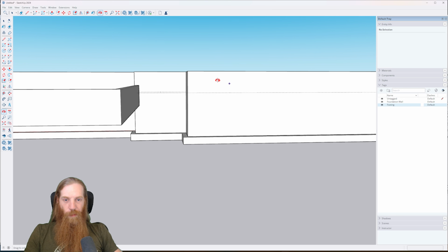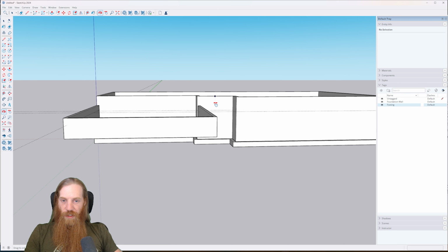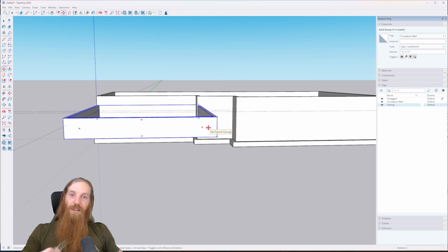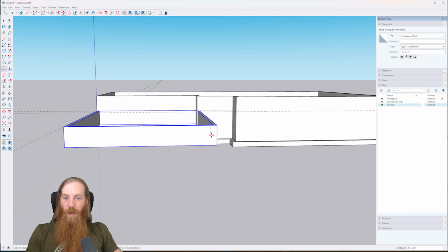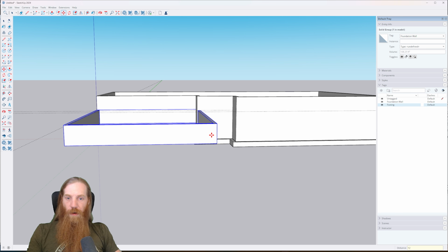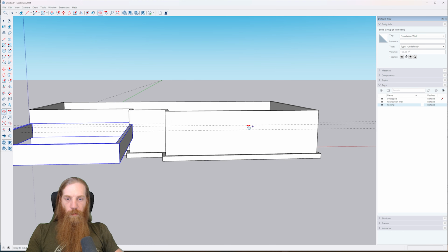Now that actually looks a little bit higher than what I probably want. So with that in mind, why don't we go ahead and select this? This is what's great about having the 3D model in SketchUp to go off of. I can very quickly and easily make design choices, like what the difference in elevation between the house foundation and the garage foundation should be, based on what I want, right? So I'm going to move it down another 12 inches. That now means that our grade is going to be 4 feet below top of foundation wall. So if I come down 48 inches, type in 48, hit enter, it gives me a new reference line.